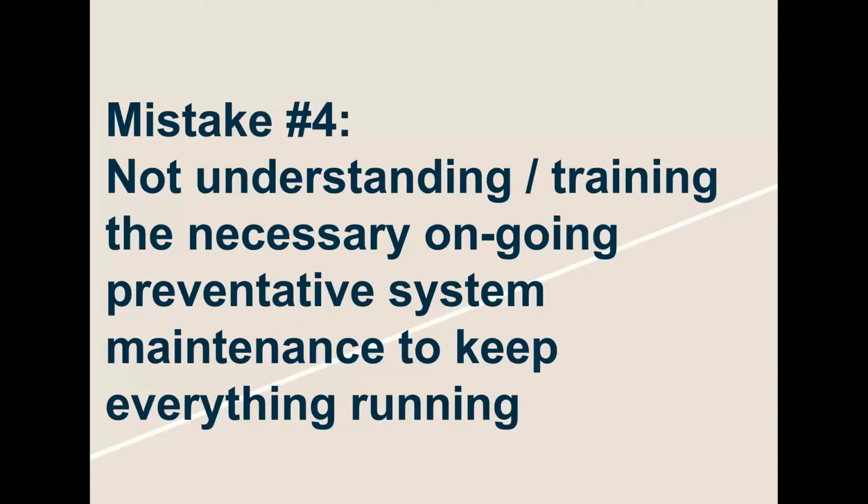So you just keep going until the point at which the end customer, the health and safety folks, whoever, are not comfortable with that error anymore. That's when you calibrate. And that's it. Some companies, no matter what, calibrate every 3 months. Some, no matter what, calibrate every 6 months. And some do a little bit of both, right? They look at the sensor, make sure what the long-term drift might be, and then calibrate based on that. So it's really important to understand the actual specifications of the sensor.